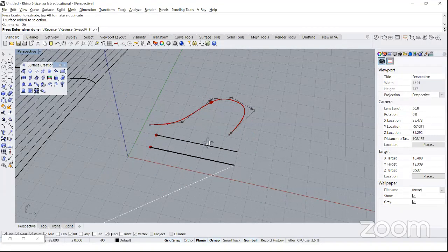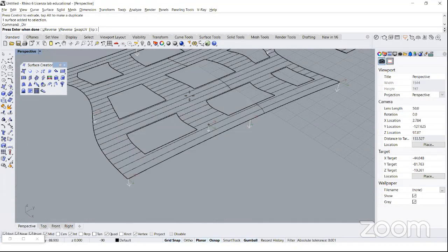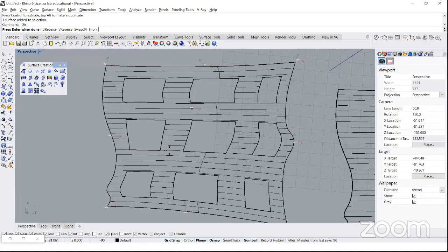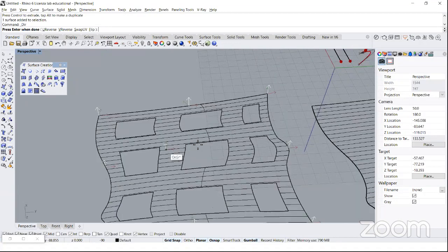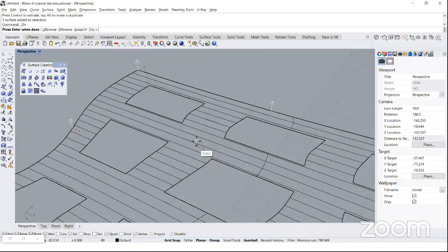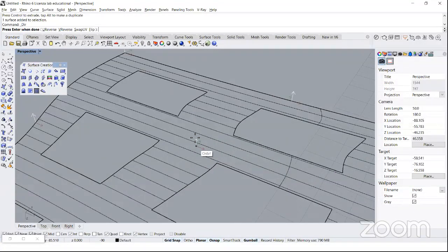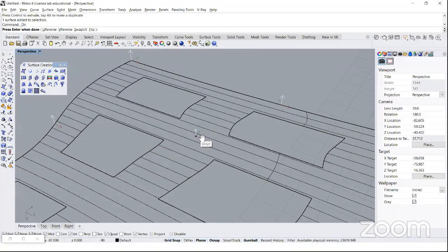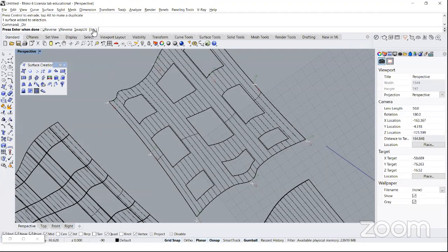And I see that if I go here at the bottom, I see this kind of orientation, because the white arrow is pointing vertically up, and then there is a red arrow to the right, and the green arrow is pointing up on the same plane. So this is a correct representation of the internal coordinate system UVW, which is, by the way, the parametric coordinate system of the surface. What happens if I just flip here?